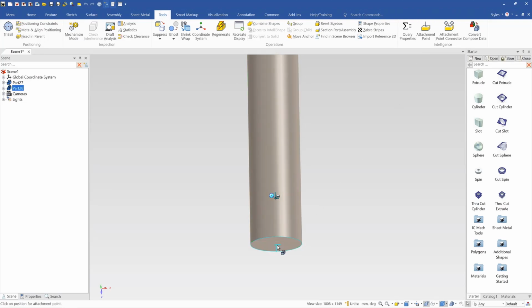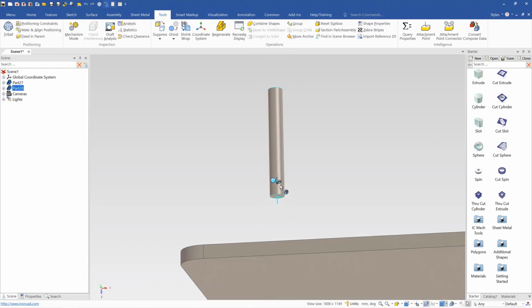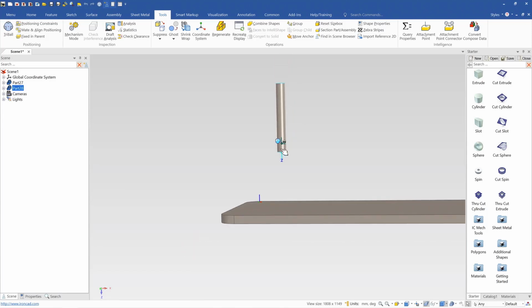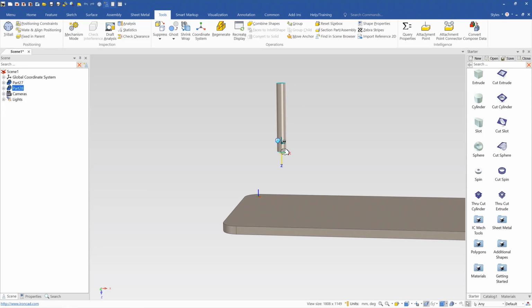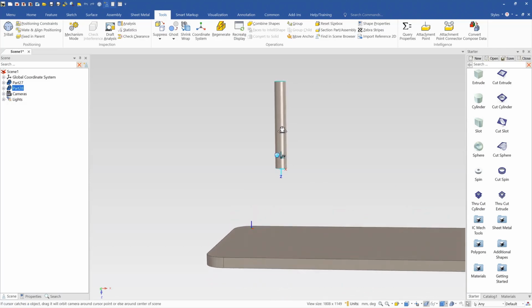Now I'll click on that. It's worth noting the anchor point also helps determine how something will position, because the anchor point is how the item comes out from the catalog. The anchor point is essentially where the mouse is. So if we had an attachment point on both sides, the model would generally connect with the attachment point that was closer to the side with the anchor, because that's where the mouse is. So if we had this same one that could attach on both sides, it will generally always use this side when dragged from the catalog because the anchor is closer to that side. You can also customize it later and choose the side it goes to from the catalog, but we'll go into that a little bit later on.